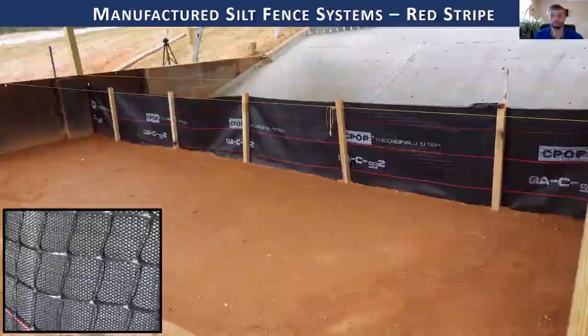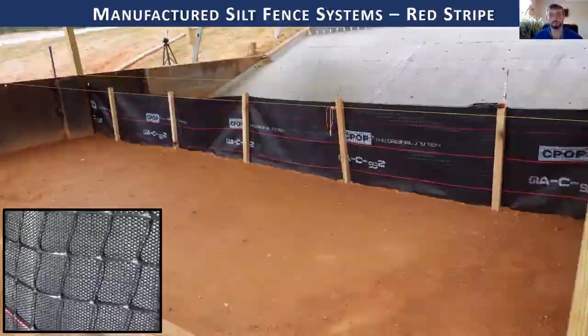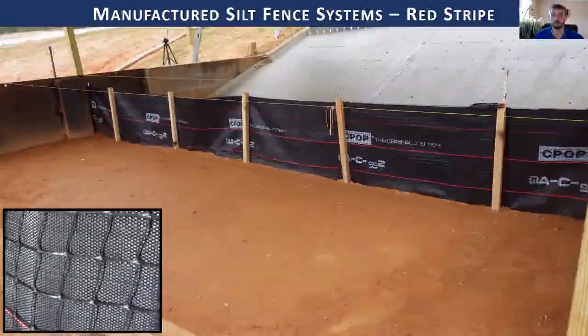Some other things that we've tested in the large-scale testing apparatus are manufactured silt fence systems. This is going back to that red stripe geotextile that we analyzed in the small scale. This red stripe manufactured system is a monofilament geotextile with a polypropylene reinforcing backing attached to hardwood stakes that are spaced 4 feet apart.